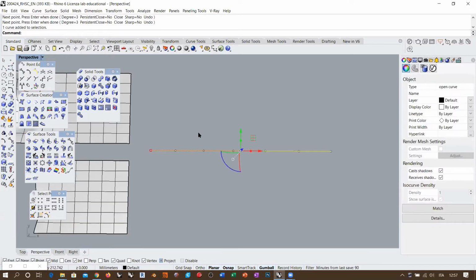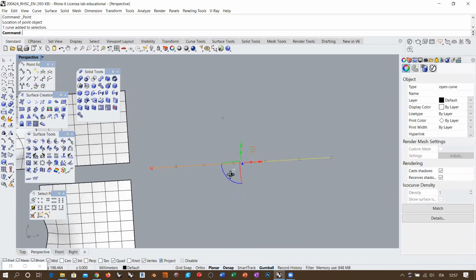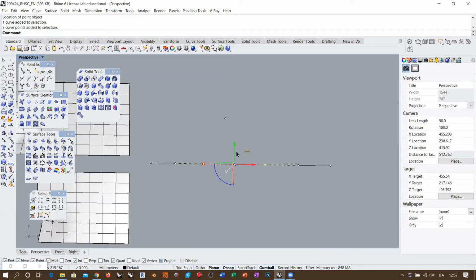And I know that if I have a curve with degree 3, I can take 3 control points and displace them and be tangent to the line that connects these 3 points, right? So if I have this line prepared with the right topology, and I want this line to reach, for example, this height, I can simply take these 3 points and move them until they have exactly the same height of the point that I want, right? So it's easy to produce some controlled deformation with the degree 3 curves, right?